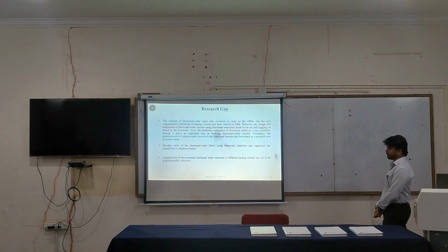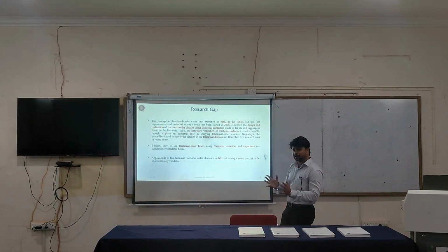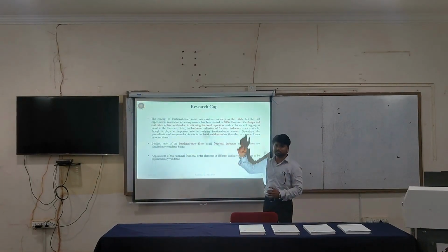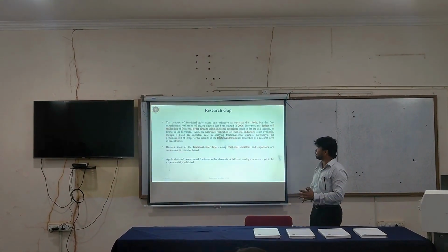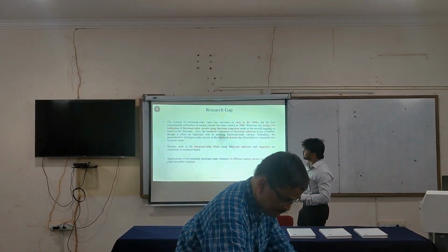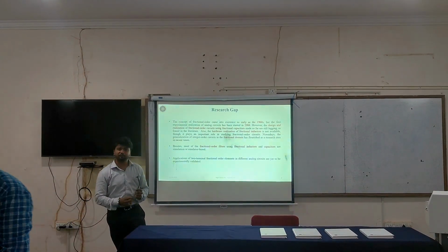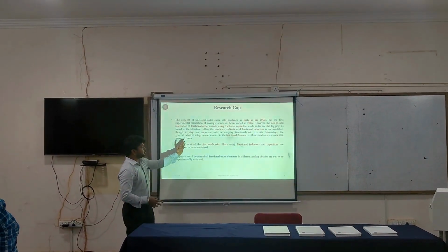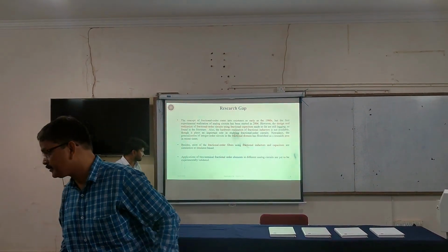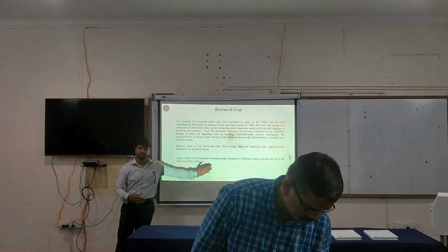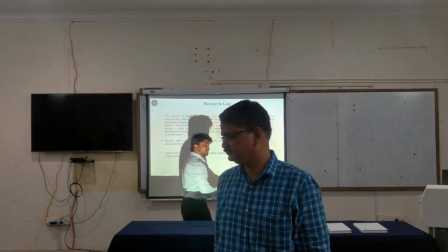Now coming on to my research gap. The concept of fractional order came into existence in the 1960s, whereas the experimental realization was first carried out in 2006. However, the design and realization of fractional order circuits using fractional capacitors are still lagging in literature. Also, the hardware realization of a fractional inductor has not been achieved to date. Besides, most fractional order filters using fractional inductors and capacitors are simulation or emulator based, and applications of two-terminal fractional order elements in different analog circuits are yet to be experimentally validated.